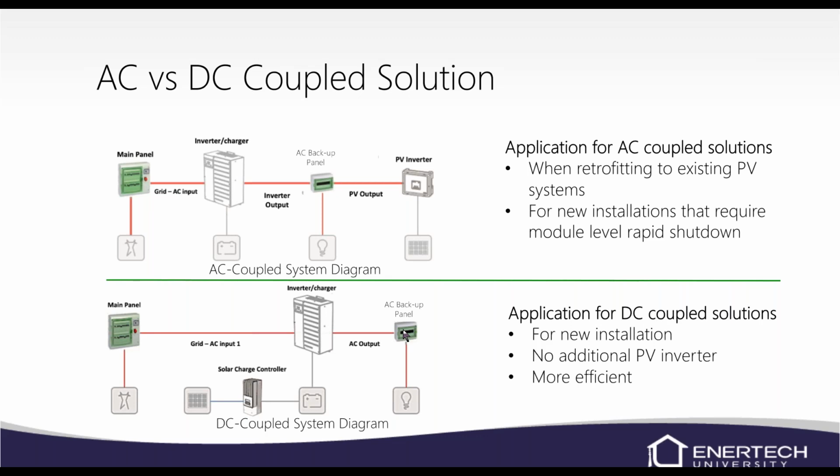So essentially what you have to do is buy another inverter that is inside of that AC coupled battery generally, and you're having to spend money on two inverters when you only need one. So that's why the DC coupled solution brings down the price per kilowatt hour installed. It is much cheaper to go that route whenever you combine everything together.